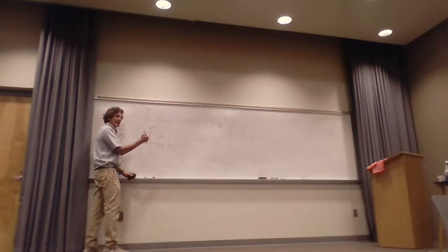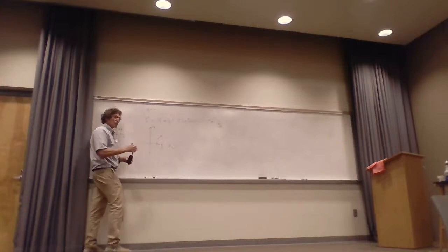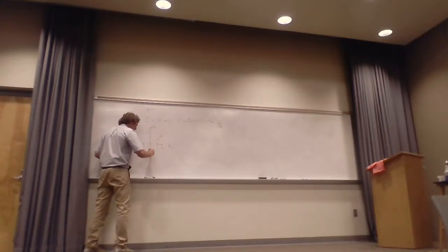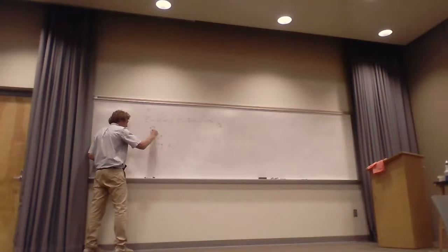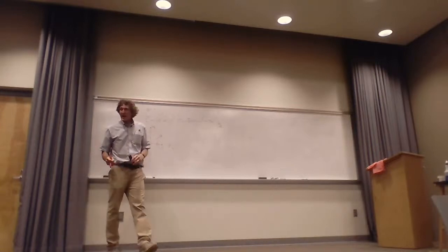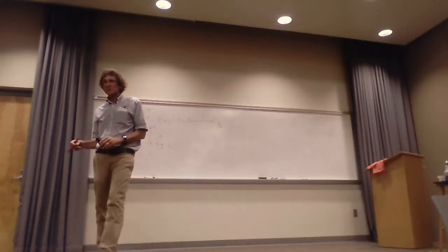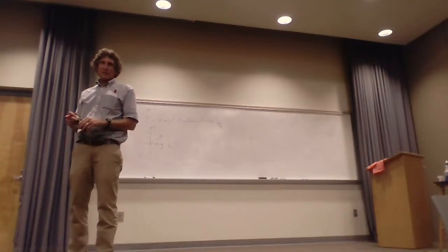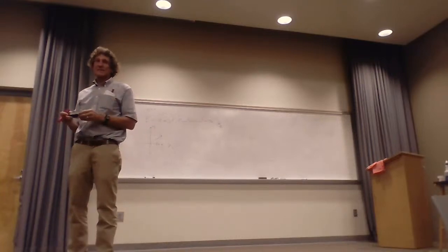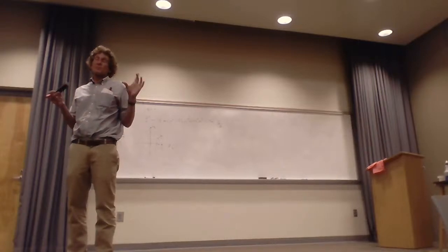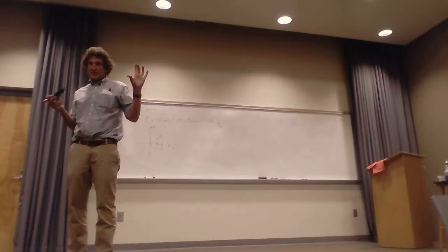This is going to be a left-hand elliptically polarized wave, and it's going to be moving this way. It's going to come down here, and then you all see what's going on? I don't ask the tilt angle. I could show you how to do it. But that's how you find out if it's left or right. If it was circular, the actual length would never change, right? Here, it's obviously changing. You all agree with that? That's it in a nutshell.